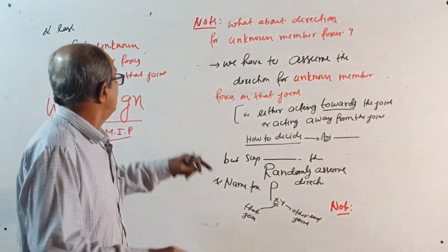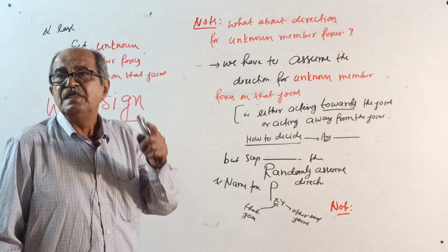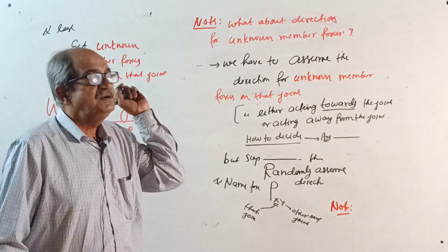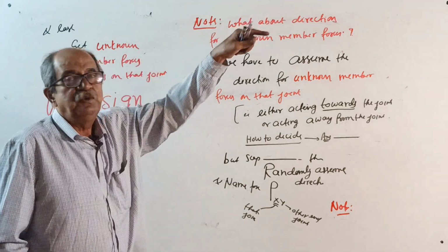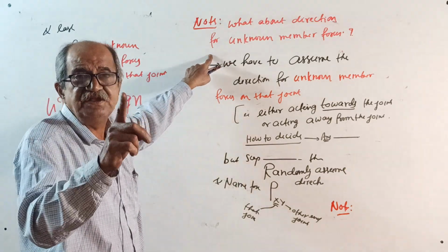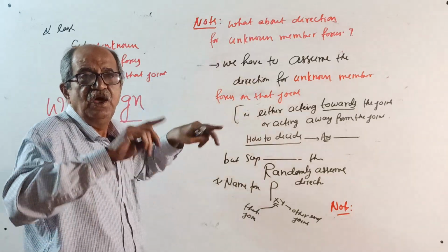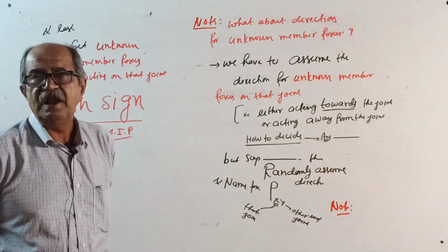Okay, then in case you get negative, that means the assumed direction for the unknown is wrong at that joint. When you put the finger in the star sketch, enter the value at that joint in a direction opposite to the assumed direction. Okay, enter the value. Over.